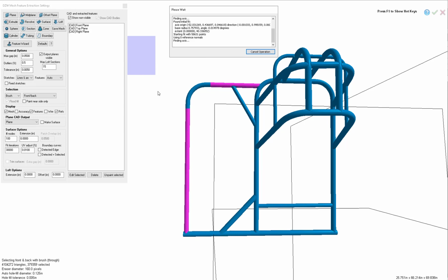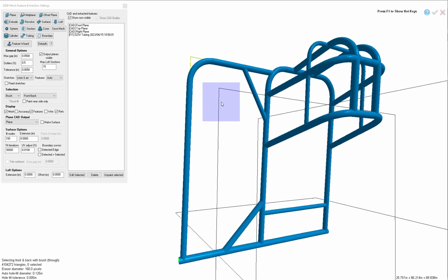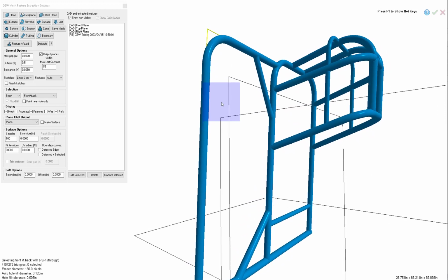And it's going to pop up here with some information. In this case, it's telling us it's a 1.5 inch tube. I know the diameter, the radius of the bends. And I simply say create it. That quick, it built you the center line. Then we'll go back and actually model this with SolidWorks, whether we use solids or use the weldment tools.